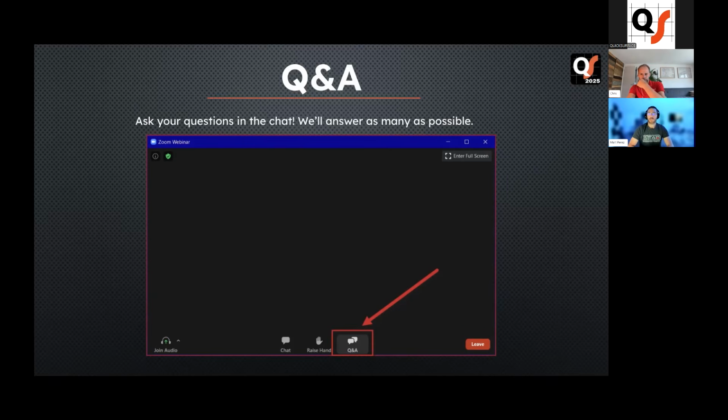So what I would say generally with that, Ricardo, is I would not use Auto-Freeform. You can try to do a custom Auto-Freeform and reduce the number of quads. But I would say that manually creating freeform on that part will give you better control. We do have a couple of YouTube videos talking about that, and we do talk about it in a course that we have on our website. But generally, if you have to really restrict the number of patches and faces, then manually controlling the freeform body is the best way to do it, in my opinion.